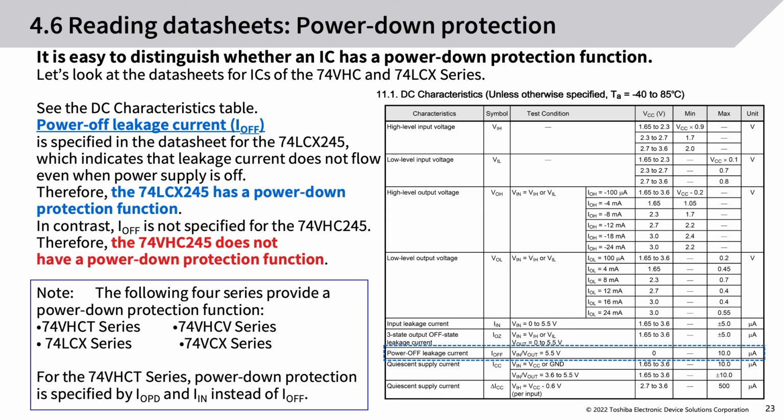In contrast, IOFF is not specified for the 74VHC245. Therefore, the 74VHC245 does not have a power down protection function.